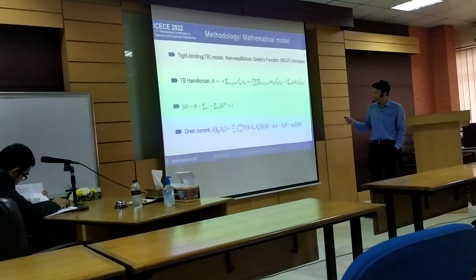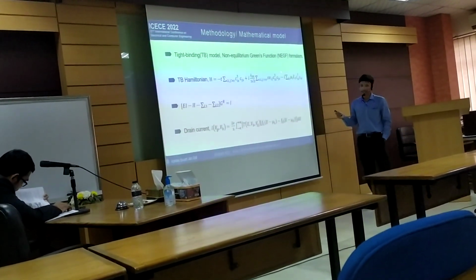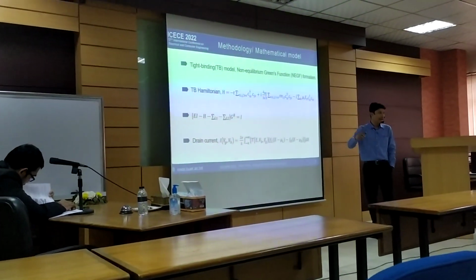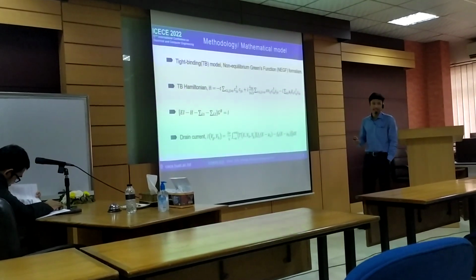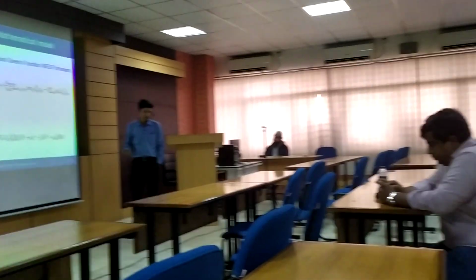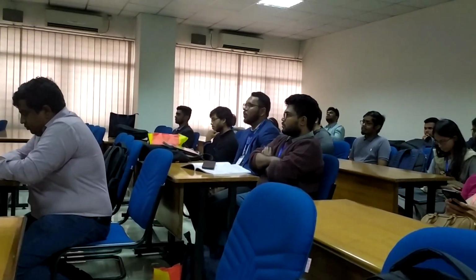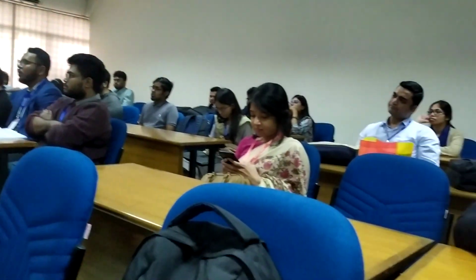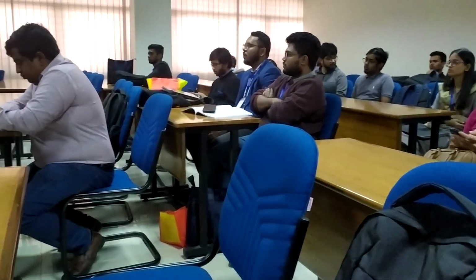And then you can see that this l basically represents the buckling height of the stanene, and this E is the electric field that will be applied from the gate. And that's why you can see the gate induced phase transition will occur. That means while we are applying the electric field, this term will actually increase or decrease, and this will actually modulate the band gap of the system. And through this band gap variation, this switching from the topological insulating state to the trivial insulating state will occur. So this actually gives us another new switching mechanism, which replaces the conventional carrier inversion process that we are currently seeing in the FET.